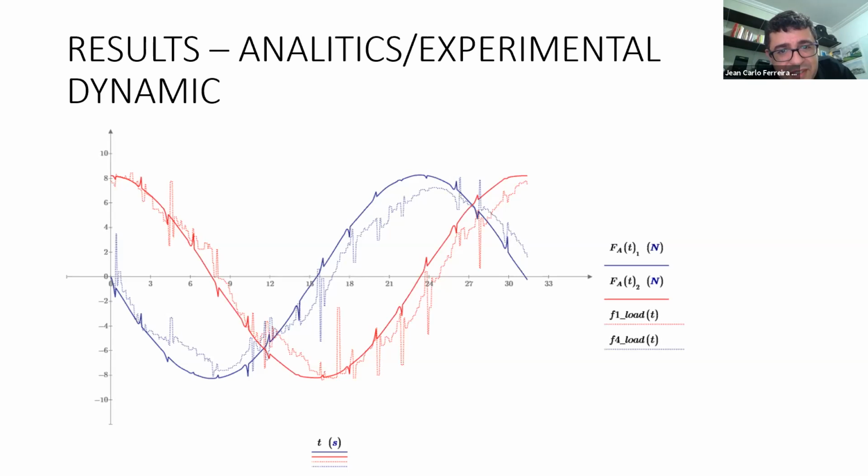Sorry, I don't understand. Please. So you had a 720 to 1 gear ratio in your motor, if I'm not mistaken. Some very large ratio in the NEMA motors that you used, right? Right. So they originally came with a very large ratio. Is the backlash coming from the motors, or is it coming from somewhere else? I'm just puzzled on how it is so high. I understand now. The backlash is from the reducer, right?